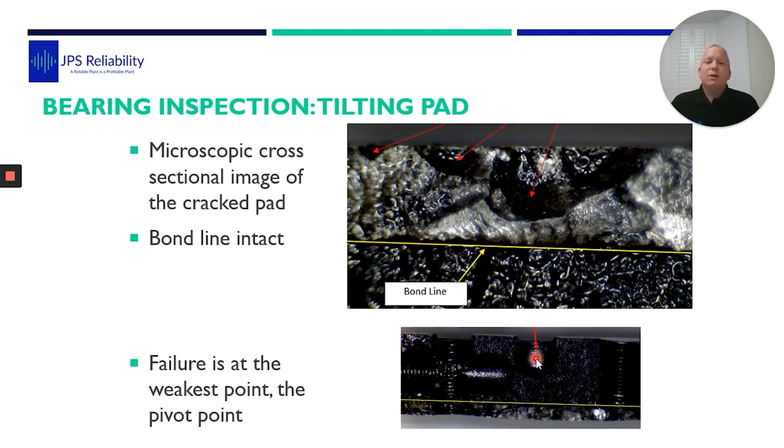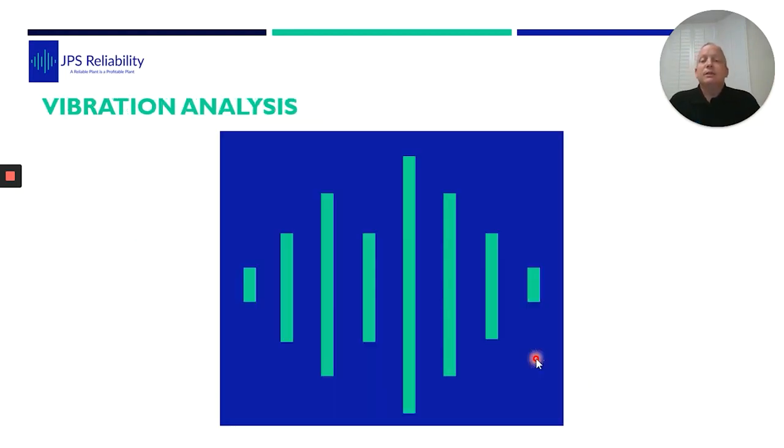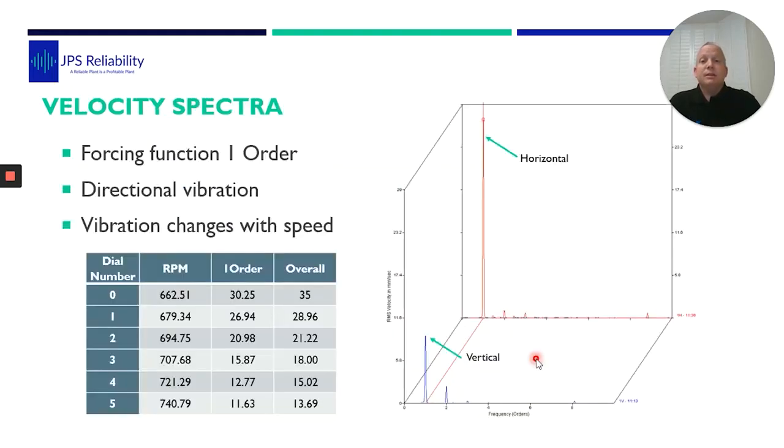Talking to operations, they said it's always the drive end bearing that fails. There's a rank of 4 of these pumps, and they're sort of all failing, and they're chasing around, repairing them, getting up and running, and they're failing, and they're trying to work out what's going on. So what we did, we went to site, and on the ones which were running, we carried out a vibration analysis survey. And what actually stood out a lot was high directional vibration.